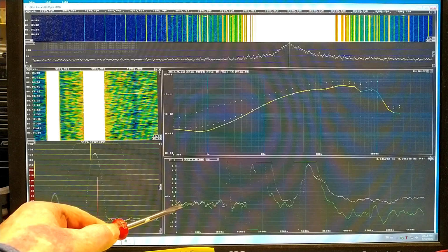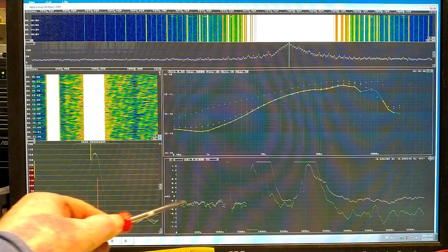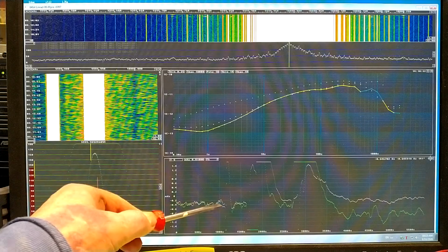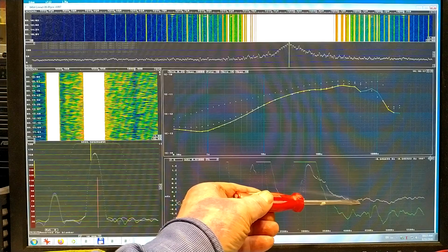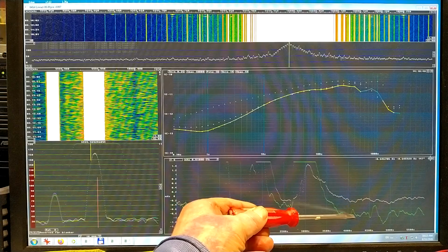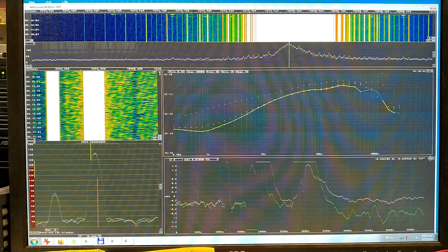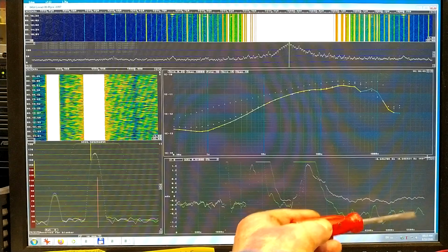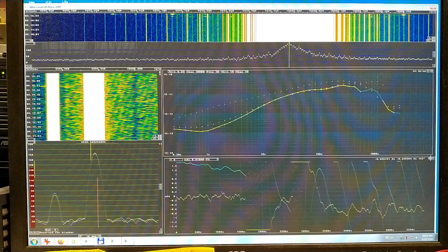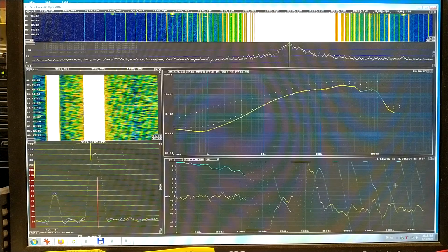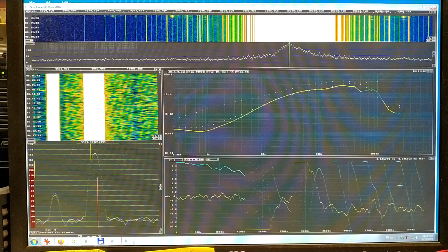Here, fairly small frequency deviations, but a lot of high-frequency noise. Here you can see the difference between my two oscillators. The channel 2 one is much better than the one in channel 1. The frequency differs by 0.5 millihertz, roughly. If I look at the phase, you can see that the phase is drifting downwards, slowly, turn after turn. So when I wait long enough, the frequency will be on the average the same.